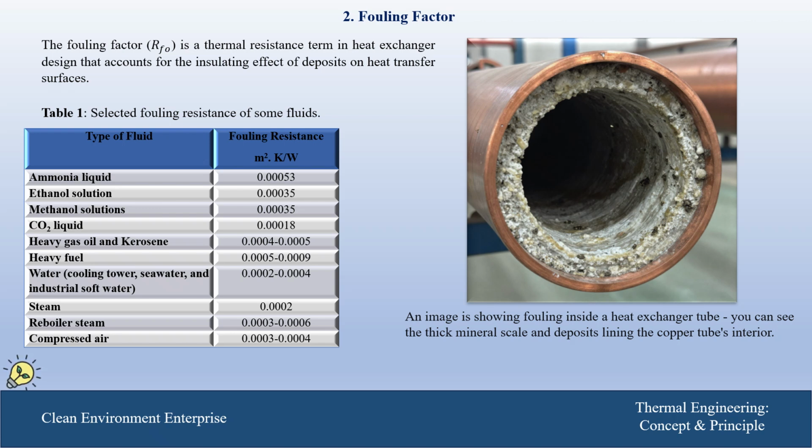This is a factor which should be considered in the thermal design of the heat exchanger because when the heat exchanger is clean, the resistances are very low and you may find that the performance is very good. With time during operation, these deposited solid materials will minimize the heat transfer and deteriorate the efficiency of the heat exchanger.